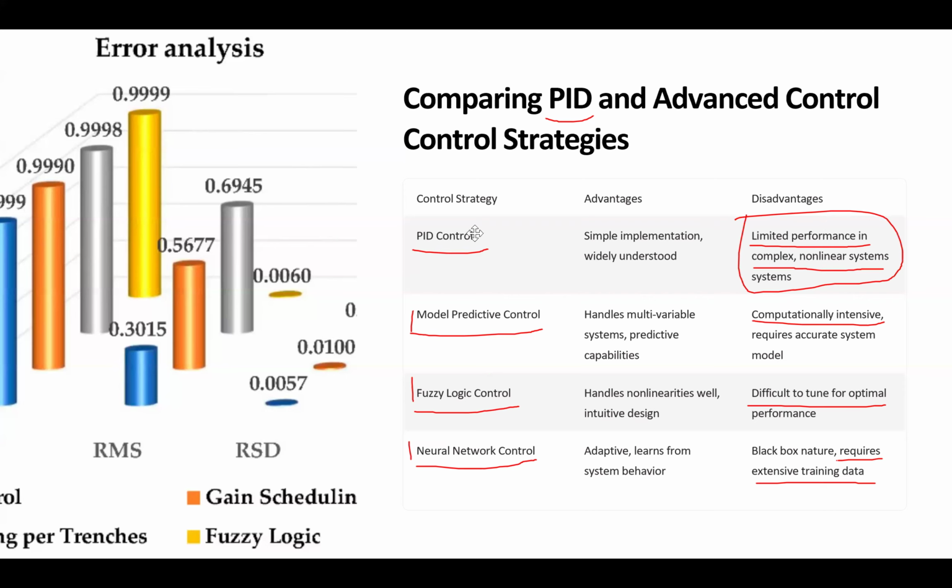Yes. So I'm assuming these sensors for the PID control, since you said at the target, they're going to be in different places in the system. The measurement for the targeted value is the measurement happening at the terminal that you connected to the grid for grid following. And the current value of your system is the output of your inverter.